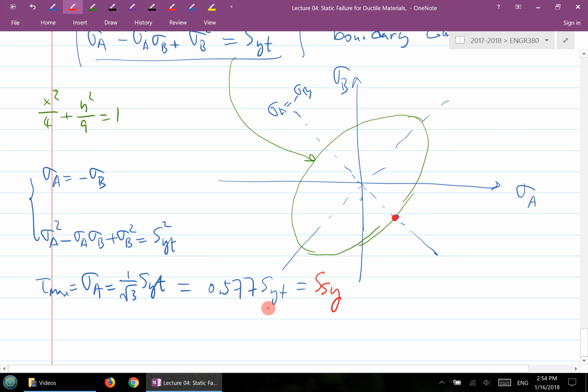So back to the MSS theory. What is the shear strength under the MSS theory? In MSS theory, SSY is equal to, what is that equal to again? 0.5, right? So compared to this one here, apparently the DE is slightly bigger. So we can superimpose the two sketches together, the DE and MSS theory.